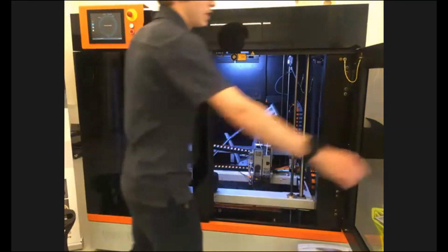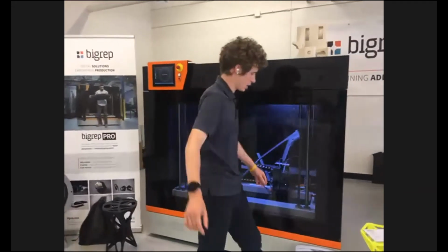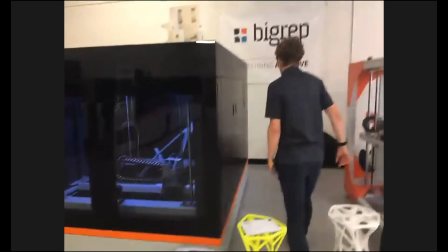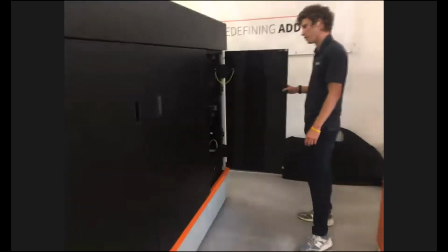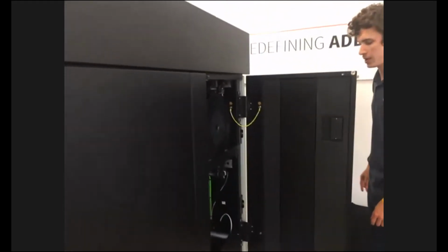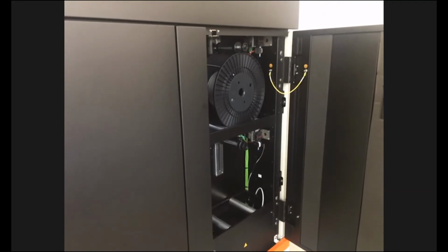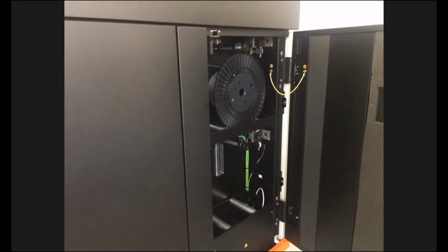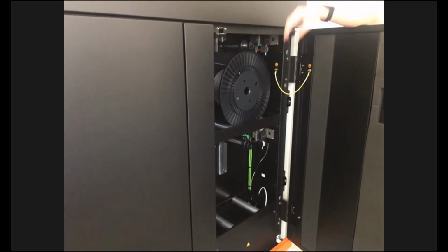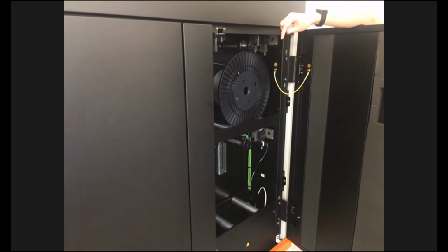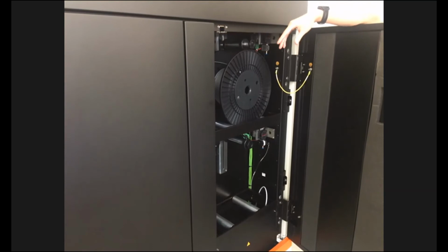With the engineering materials that we can run on the printer, there are a couple other options and features that we need. One is the pre-drying of all of our filaments that require it. Things like water-soluble materials, ASA, and I know TPUs are particularly temperamental with the atmosphere and moisture. So we have 2 chambers here and then 2 on the other side, just to make sure the material is in peak condition before it's printed.